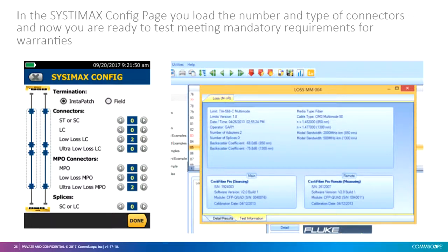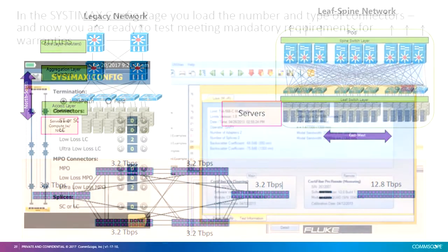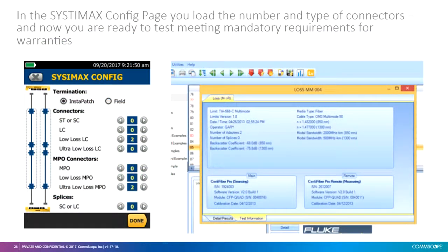Once you have set all this configuration, you can proceed directly to testing. It can compare the actual measurement against the link loss inputted during the design or installation. It can validate, and then you can directly submit these files for the ComScope warranty. Okay, this is the link loss integration. Most of the projects, we are now pushing our partners, end users and consultants to follow this. It will be a very handy tool for us to issue the warranty, and even for the end user and consultant to ensure that the design is going to work for them.